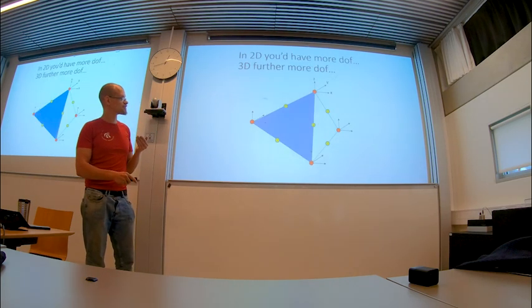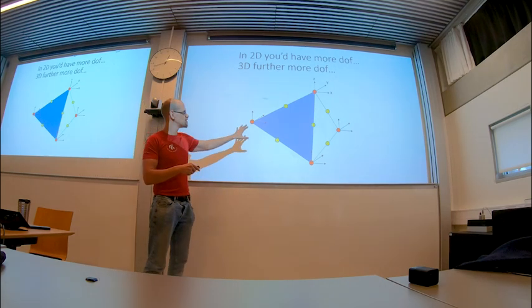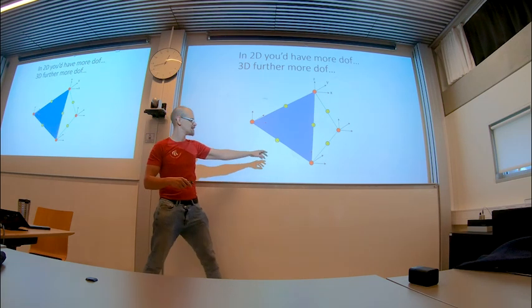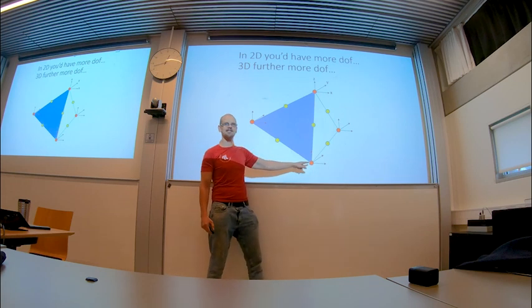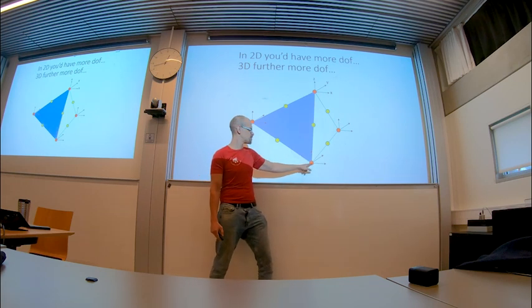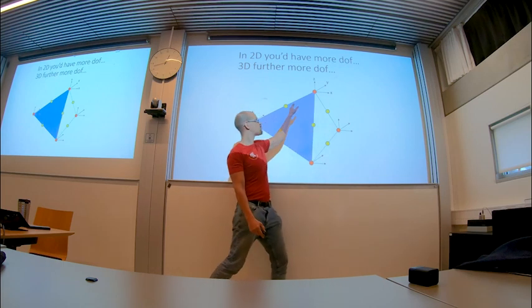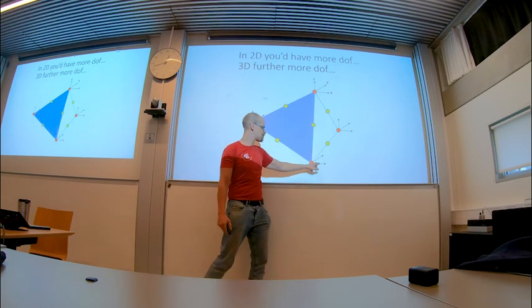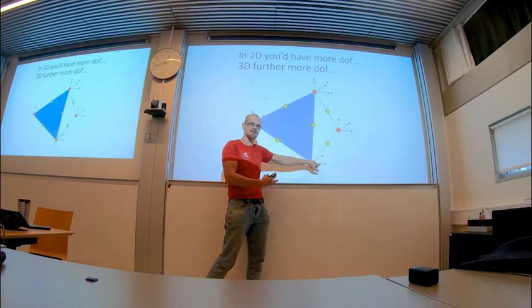And if you want to do it in 3D, then every corner has some degrees of freedom, but this remains the same thing. Technically, if you lock all of them in space, just anchor them in space, and then you release 1 degree of freedom. You build that stiffness matrix by moving this by 1 unit, and then assigning force distribution on all the other corners. So when you pull it by 1, it creates some reaction force that you must know somehow. You can test it experimentally.